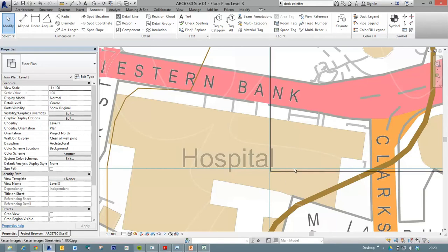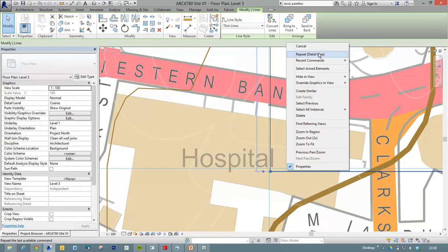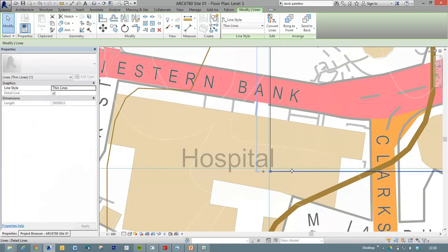And what you might notice is what it's doing by default is it's offering us just one of those lines at a time, and often that's very useful because you can just pick up one element and edit it. We want to select all those elements, and there is a shortcut which is Tab. So you see when I hit Tab there, it changed to all of those elements, or if I right click, it does offer us select joined elements there. So a couple of useful tools there. I'm just going to come back out of that, use Tab to select. So I've now selected that